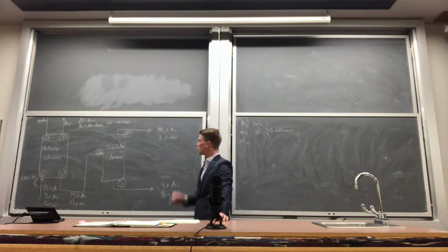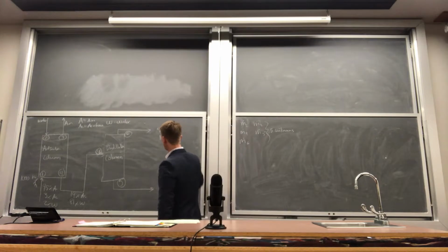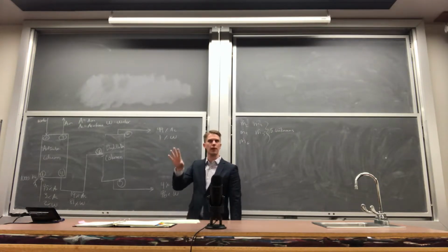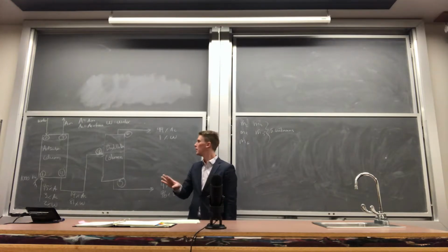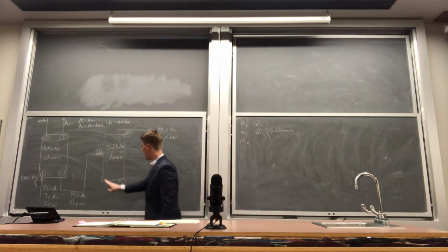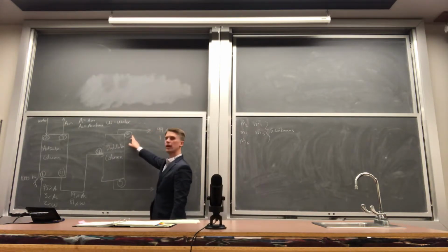So we have a suggestion to start with the distillation column. Let's just quickly do an overall material balance on the distillation column, right? This is a continuous steady state process, right? So that means in is equal to out. That is our balance, that's our default assumption unless otherwise stated. So coming into the system, we have M4, coming out we have M5, coming out we have M6.